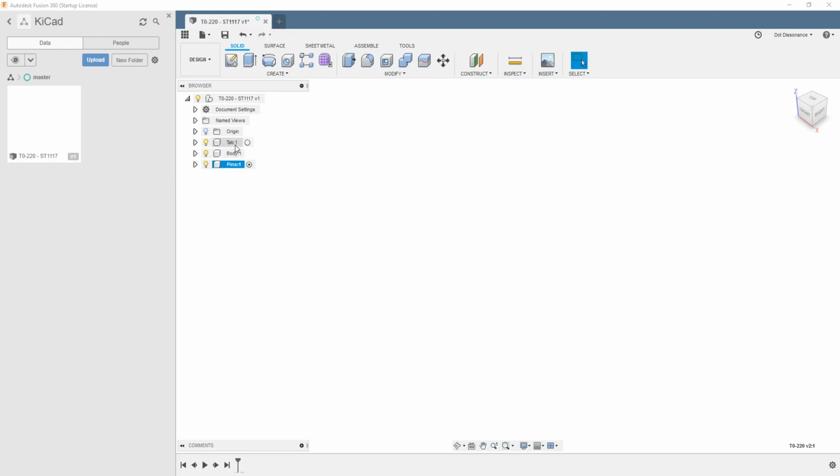Okay, so we'll go over here and we'll create the tab structure first. That seems to be the easiest. Now, when you're working with an assembly, a thing that Fusion does is, if you're used to doing things like up to last, or you're making a whole extrude cut and it's going through things and you say through all, it is conscious of the fact of the other parts in the assembly.